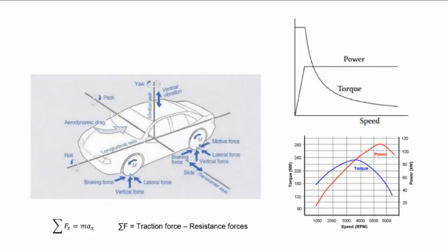The base of the longitudinal performance of a vehicle will be the fundamental equation of longitudinal motion, where the dynamic features of the vehicle and the impact of the external environment are quantified. This will involve the evaluation of resistance. What's the resistance? Resistance is what counters movement. Okay, as a way to calculate the actual performance parameters of the vehicle and the influence of adherence on the tire-road contact surface. It's mainly important.